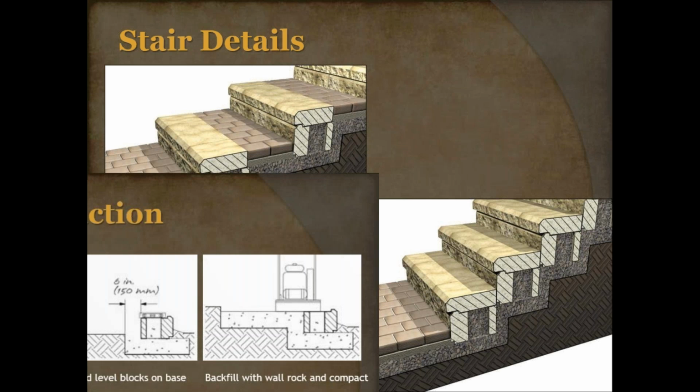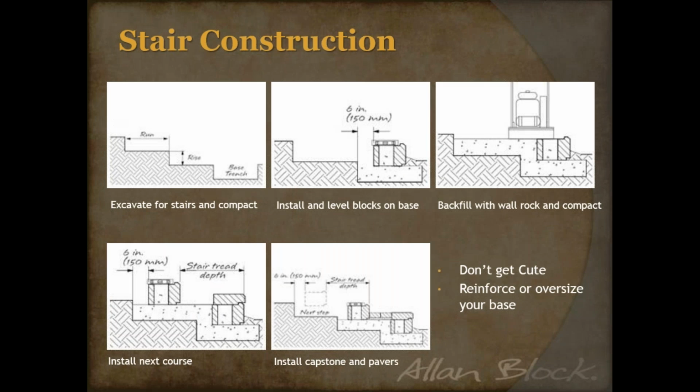And then obviously during construction, I got a note down here, and you can see it. It says, "Don't get cute." It's easy for me to draw these nice, clean, crisp lines in a detail, but to be perfectly honest, you're going to blow this all out when you're building stairs. Remember, this is a point of traffic, and so you're going to have people walking on there. So go ahead and bring in more rock than you typically use. And so what we want to do is just make sure we've got a base that is level, base that is compacted, base that is sound.